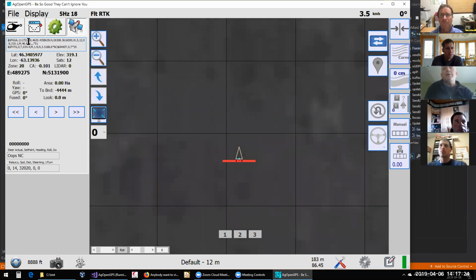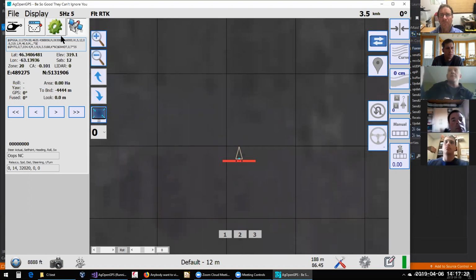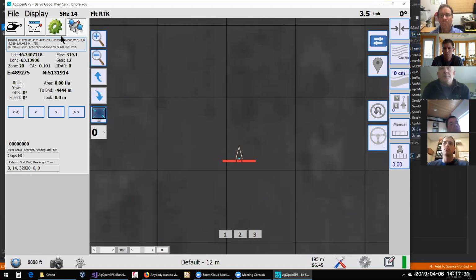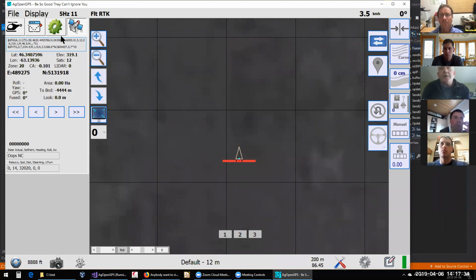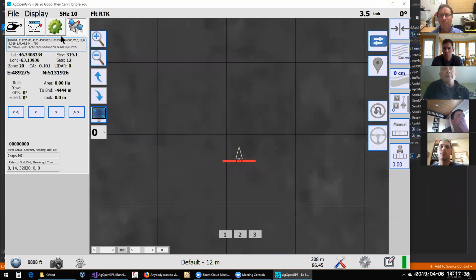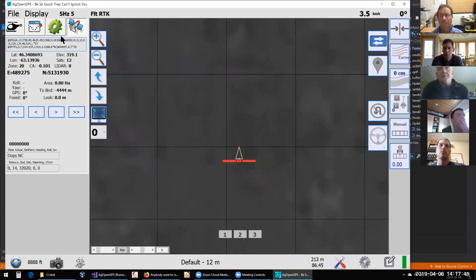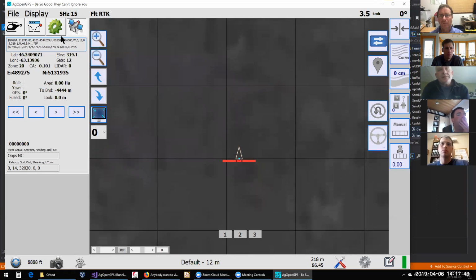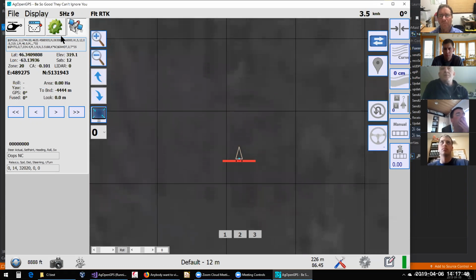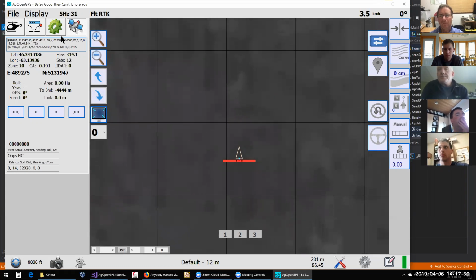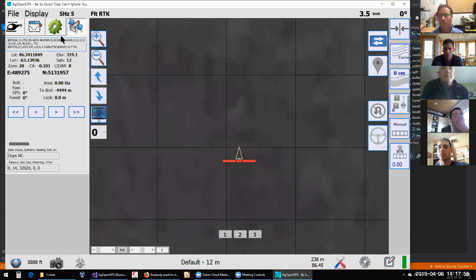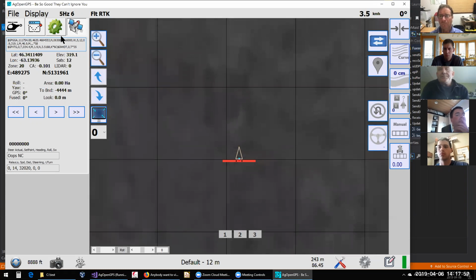And technically, you could calculate speed based on your fixed-to-fixed distances. So you could actually eliminate VTG as well, like in a future release or whatever, just by calculating it based on your fixed distance. But then that's not super accurate either. The speed that comes from the GPS unit is extremely accurate. Hate to lose that. But if you're just sending VTG and GGA, then it works flawless.